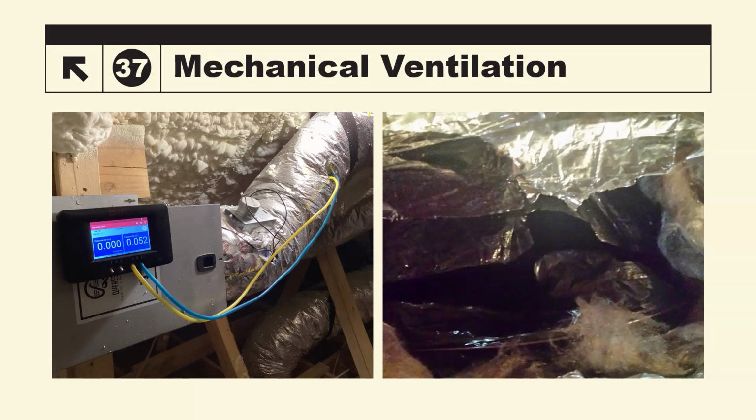But like I said, this was kind of an earlier, only way we could do it. When it first came out, it was proposed that we have a test station where the mechanical installer puts in a hard pipe with a hole in it that we could test without cutting into ductwork. That was not approved. So we're just left to our own devices to figure out how to get this to work. And how we get it to work is we try to prepare the duct for surgery. We always called it open heart surgery. Put tape on there first, cut through the tape. That way the duct holds itself together. But a lot of times guys will forget that, and when you take that probe out, it just ends up shredding the inner liner of that duct.